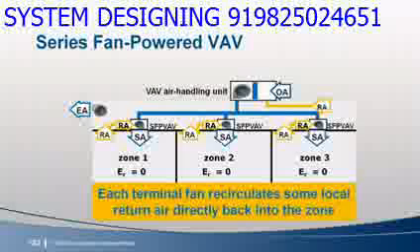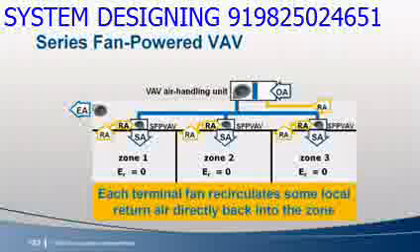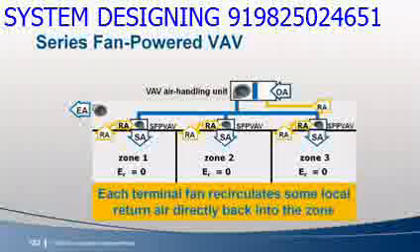For example, if recirculated air from a zone is ducted directly to the intake or inlet of the fan power VAV box serving that same zone, the recirculated air in the secondary path is the same quality as the air within the zone itself. In this case, E sub R would be 0.